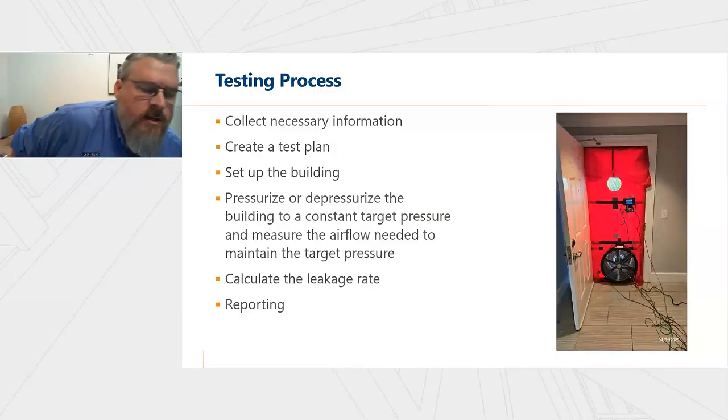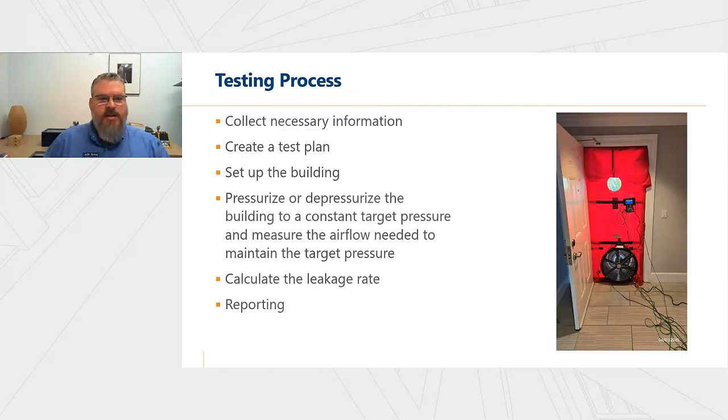The second phase is whoever's going to be doing the testing, whether it's a building enclosure consultant that's also doing the testing, or if you have a separate test agency, they're going to create the test plan. So they're going to lay out what all the roles and responsibilities are for the people participating in the test. And it's not just the testing agency. It's going to be the construction team, the general contractor. It's going to be probably the mechanical engineer. You're probably going to have somebody on site that knows how to set the mechanical equipment up and knows how to reset trip breakers, because that can happen.